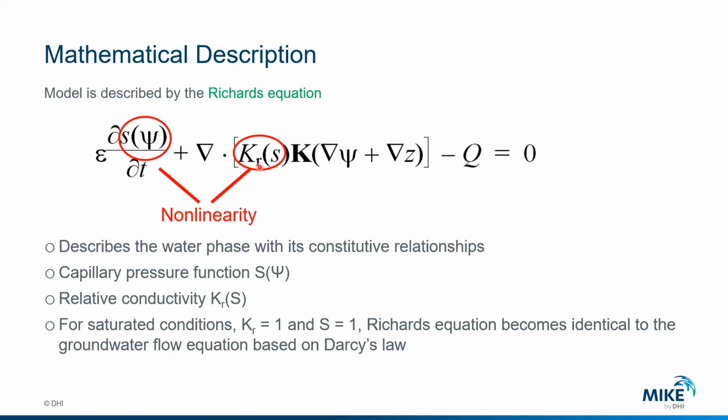At that time it was proposed that the relationship between hydraulic head or pressure head could be related to saturation, and that the way the fluid moves in the unsaturated system depends on the conductivity, and this conductivity is no longer the saturated hydraulic conductivity, but now becomes a conductivity function which depends on the current saturation. So all this interconnection of parameters makes it difficult to solve.